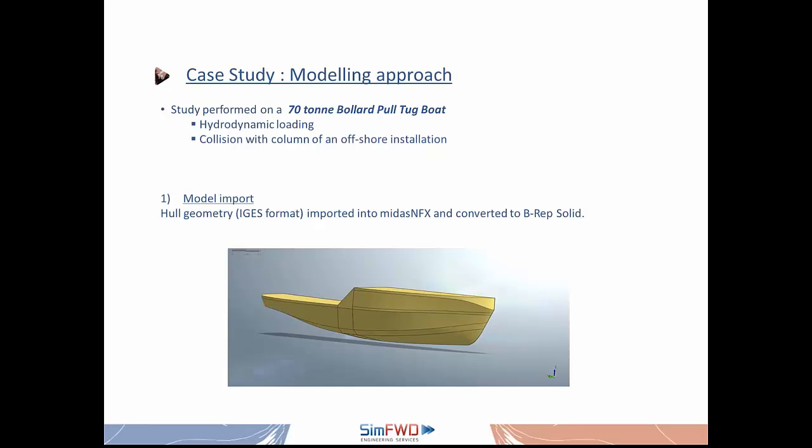In that case, we will start with the setting up for the hydrodynamic analysis, and to do that, one would have to actually convert the imported model. A model coming in as an IGS will probably consist of different faces and surfaces, and possibly also lines. So one will have to convert the geometry into a BREP solid in order to be able to perform a Boolean operation that we will see below.